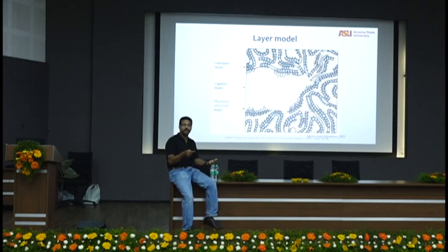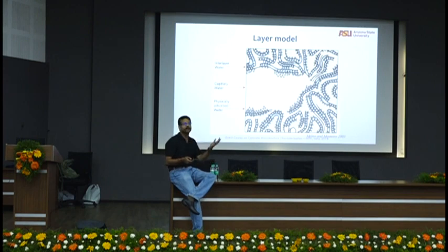You divide that mass loss by the mass loss for pure 100% hydration, that's 0.23, and you get the degree of hydration. Is that how you calculate degree of hydration? So this is one way. This layer model is the basis for calculation of degree of hydration. This is what they use.